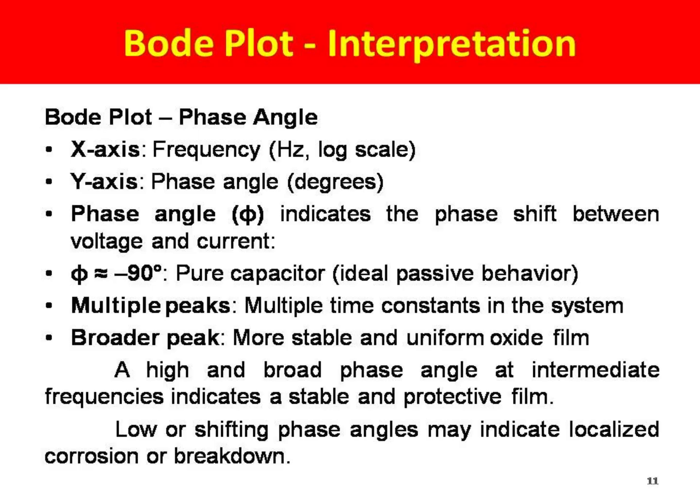In terms of the Bode plot with phase angle, the x-axis is frequency and the y-axis is phase angle, and phase angle indicates a phase shift between the voltage and current. If this phase angle is equal to -90, then it is a pure capacitor, or ideal, and the material has ideal passive behavior.